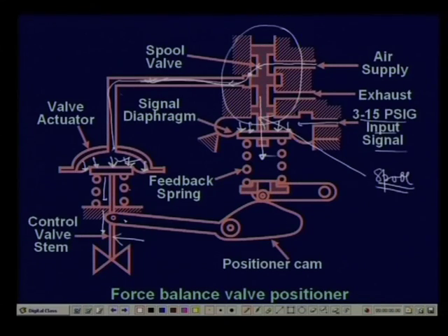On the other hand, because of this mechanism, when this comes downward, there is a force applied upward. So, you see it's a force balance principle. Finally, whatever pressure is being applied here must be balanced by the spring force as well as this force.